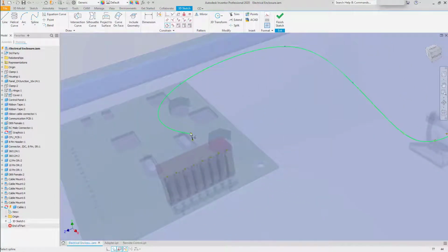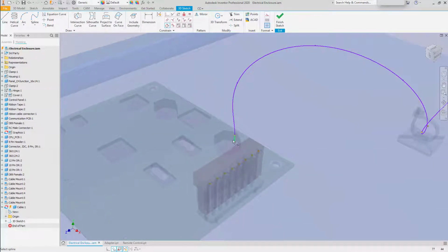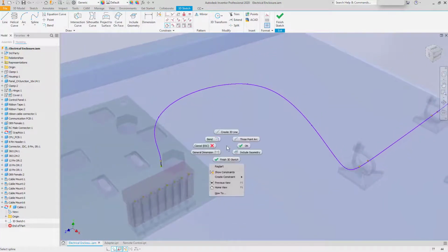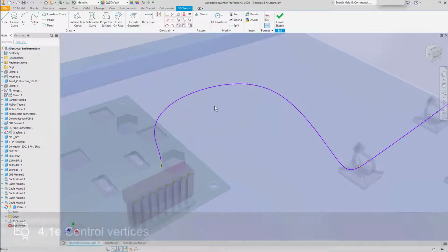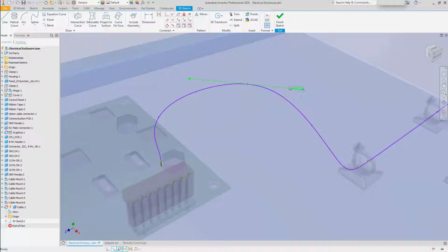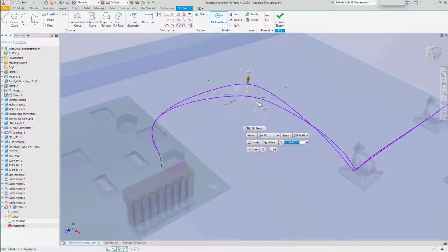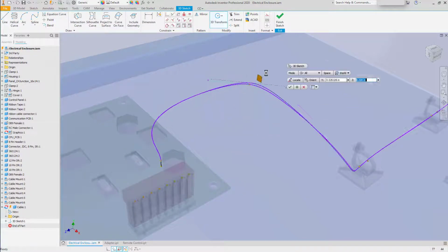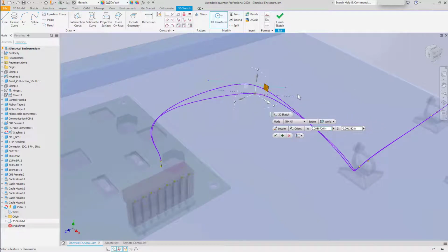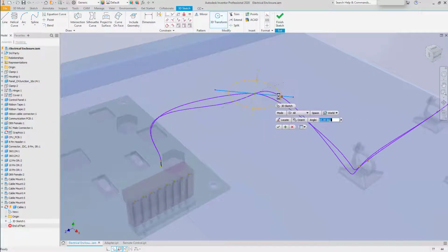In some cases, where there's extreme curvature changes, you may get the spline flipping directions. Once you have objects in place, you can select any of the points and activate the handle to change the curvature weight. You can also use the 3D transform tools on any of the points to move them in any particular direction or to move them through a plane. Selecting the handle will allow you to apply controls for direction as well.